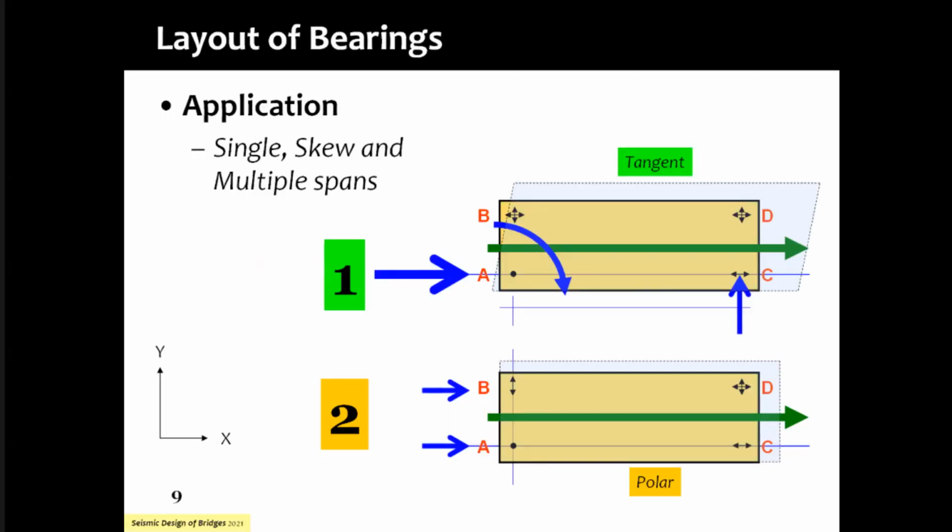I talked about the number of pieces in a bridge. If you have too many pieces, you have too many bearings also. And one of the issues that is plaguing bridge designers is which bearing to use and where to place which bearing. It's still a crisis, and I believe that it is time to sort this out from a very fundamental behavioral point of view. What is good for thermal expansion and contraction is also good for the purposes of seismic shaking.